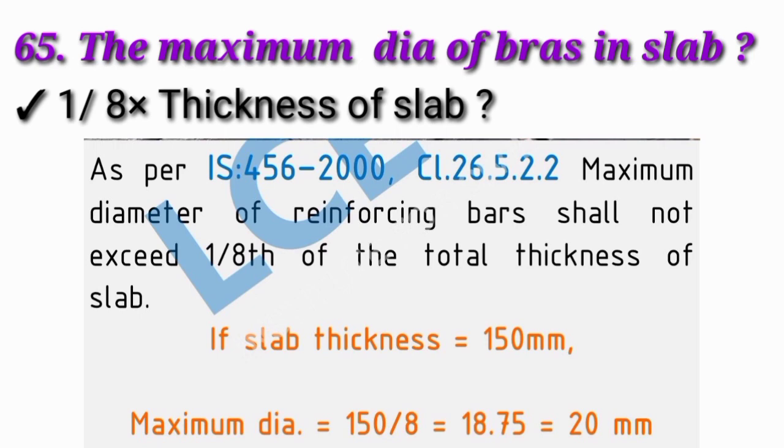which is 18.75, rounded up to 20 mm. The maximum diameter of bar used in slab is 20 mm only. This is the maximum diameter bar.